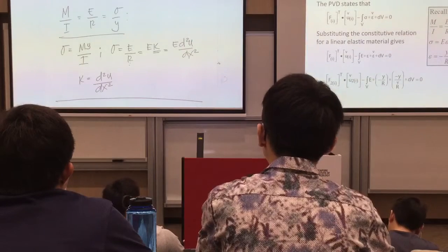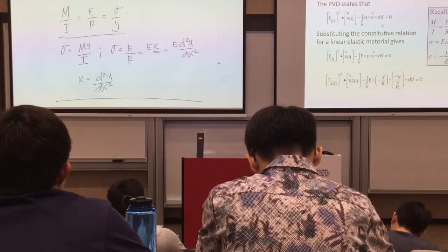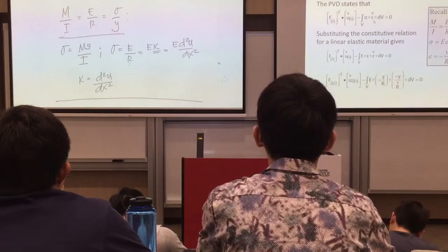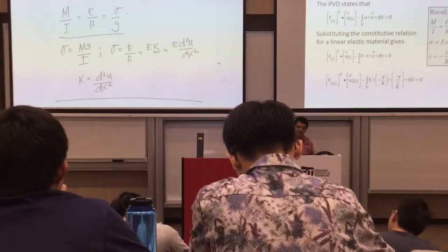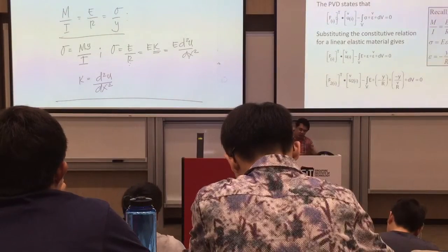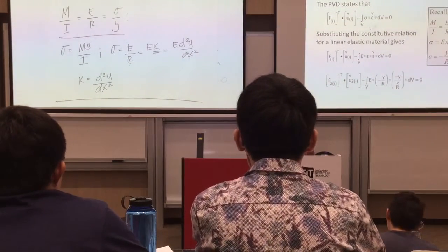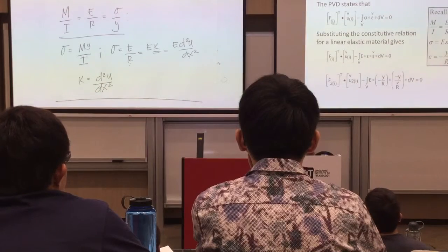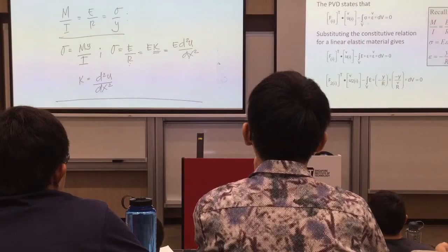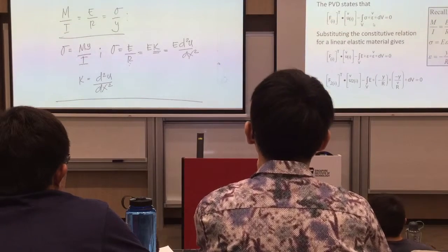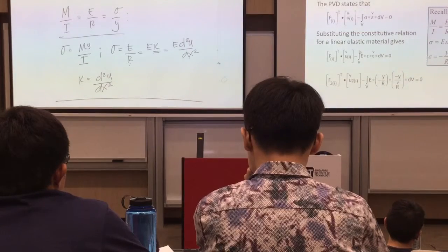So again, here you go. So you have now here stress multiplied by the strain. So we got this one already, your PVD. So this one is your work minus the strain energy is equal to 0. So your work done, force multiplied by the distance, is equal to your stress multiplied by the strain, the area under that rectangular curve.